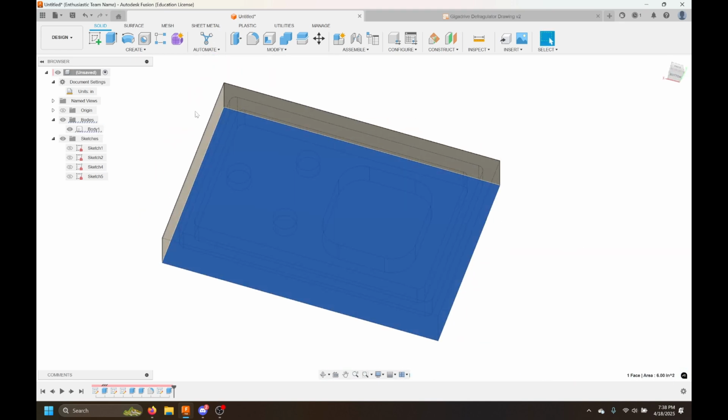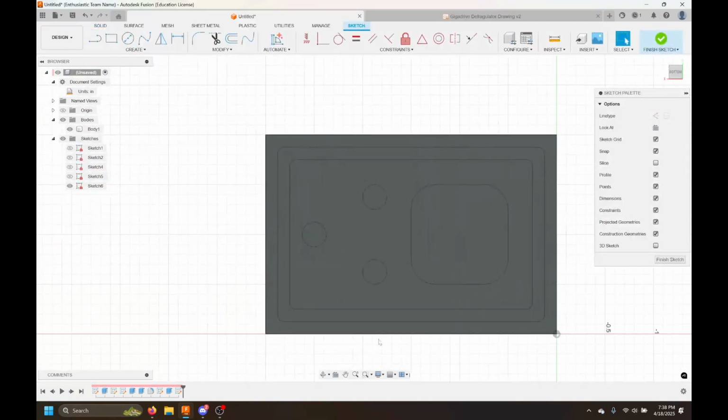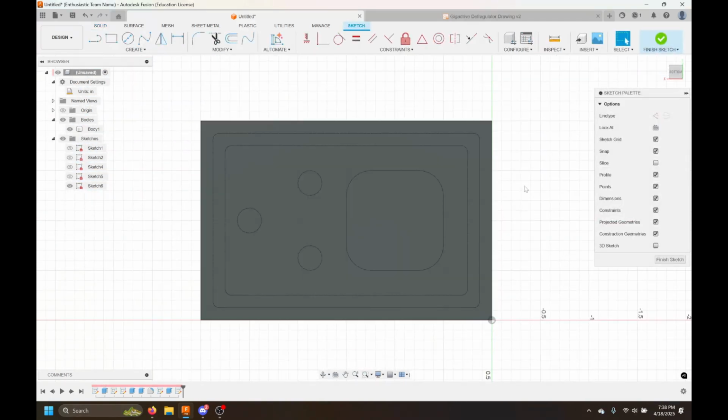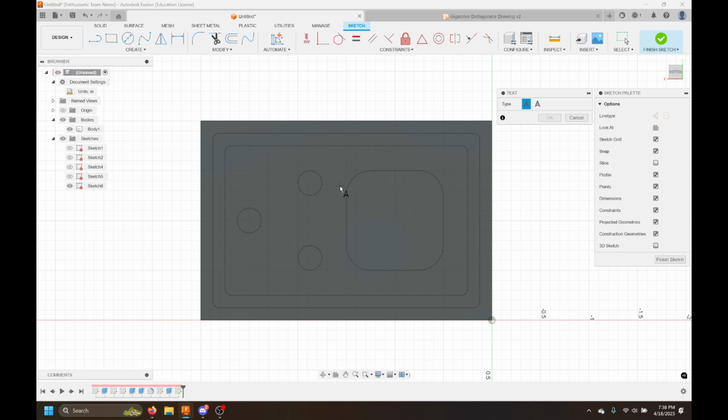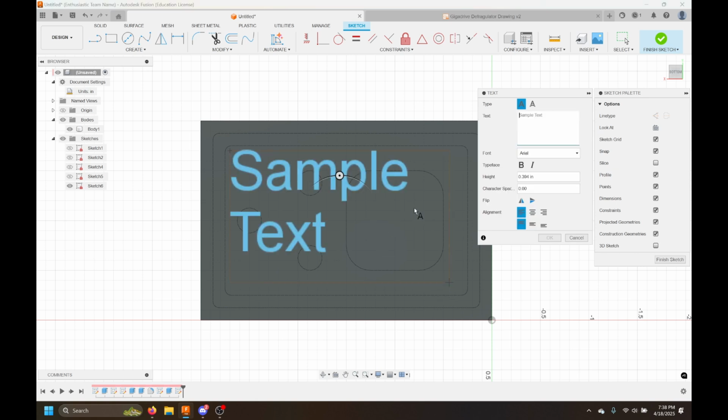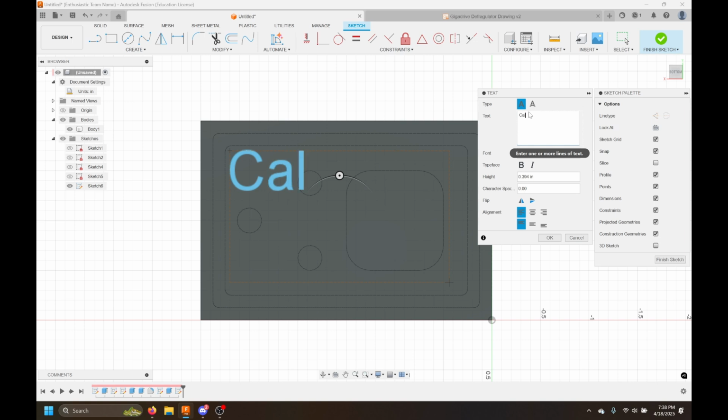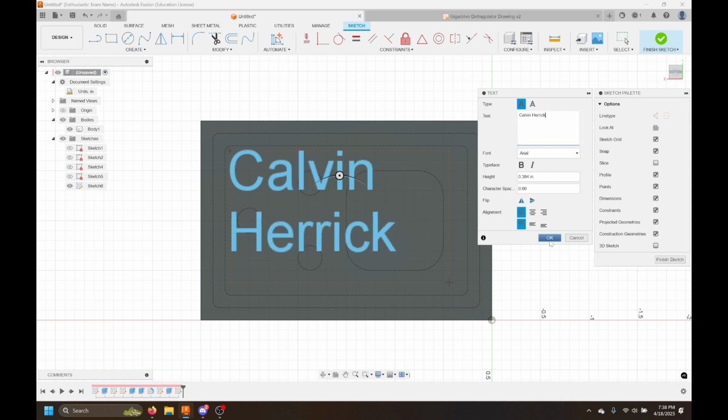I'm gonna make a new sketch on here. This is where we're gonna put our names. I'm gonna put some text on here. Text is under create. It'll just be text. And we're gonna center this right in here. So we're gonna make our text box first. Just drop that down. I'm gonna type my name in. Doesn't really matter right now.